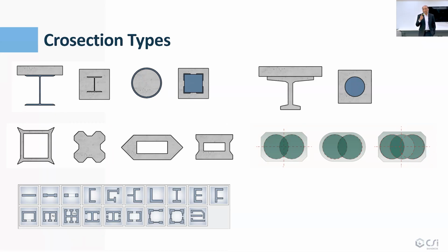And then even confined, the green ones that you see here, they are the confined columns coming from AASHTO and other Caltrans agencies, which use special types of reinforcement patterns to create their bridge piers. So we can see here that it's a large variety of cross-sectional shapes, configurations, and materials that are used. So now the question is, can we develop a unified equation to compute the basic capacity? And I'm talking about now axial flexural capacity. I'm not talking about shear at the moment.